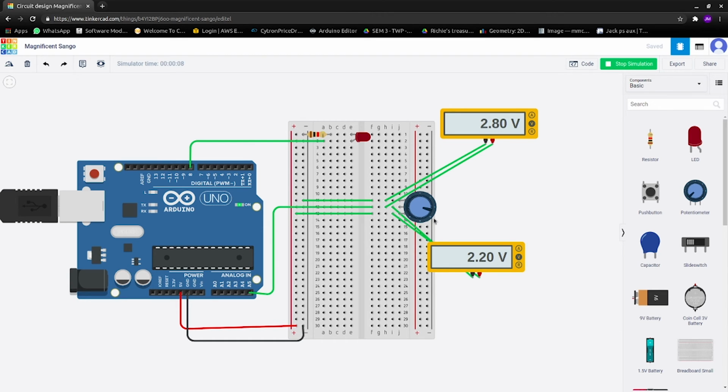And we should see that this potentiometer serves as a sort of divider of the voltages. If you guys have studied Form 4 or Form 5 physics, you should remember how to divide a voltage, and that's with both sides having different resistance. So in this case, that is abstracted from you, and this is done by the potentiometer itself. As you can see, the top voltage and the bottom voltage always add up to 5 volts. All that is happening is you're deciding if you should drop more on the top side or if you should drop more on the bottom side.